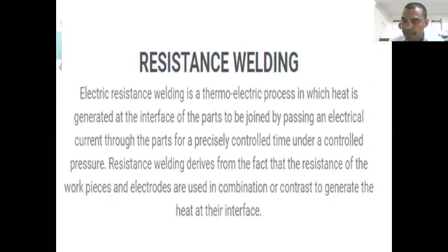I repeat again, in resistance welding, a low voltage, the voltage may be 1 volt, and a high current, it may be 15,000 ampere, is passed through the joint for a very short time.